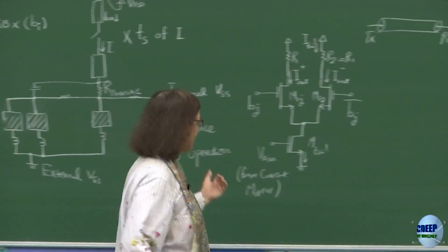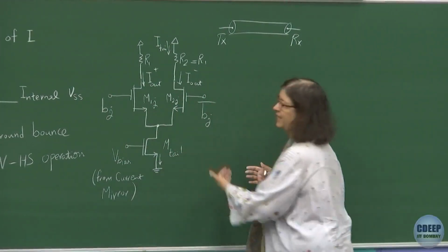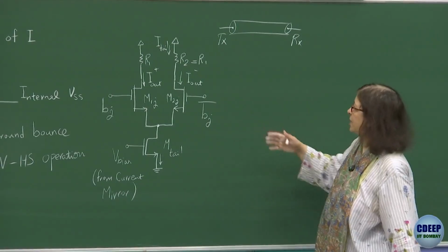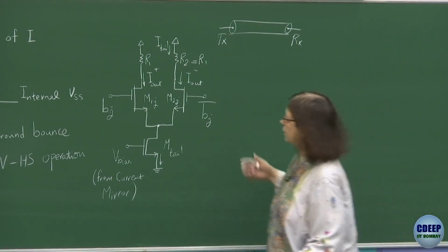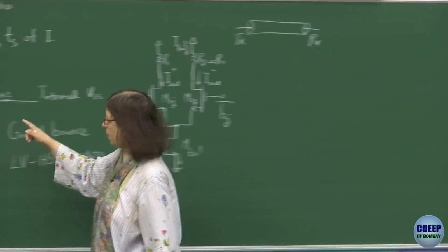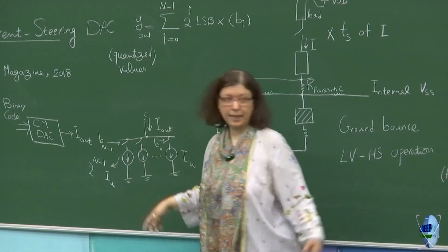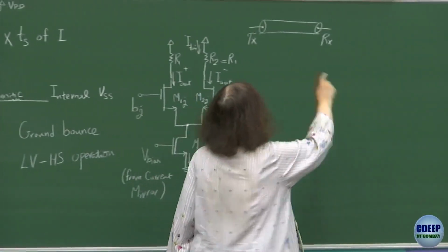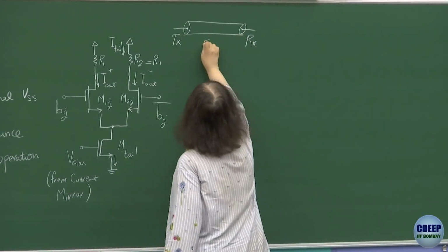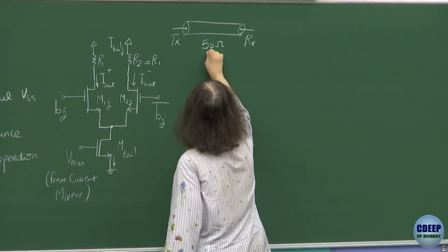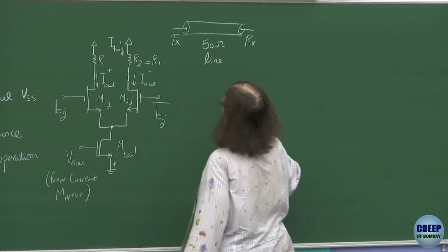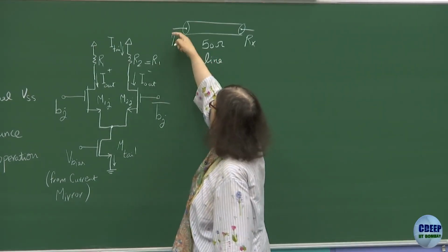And this is actually in the form of a DAC. So what they do is that you don't need to connect resistors for all these connections. It's actually only one resistor. And if this is a 50 ohm line, which is the standard, it's enough to add 150 ohm here.